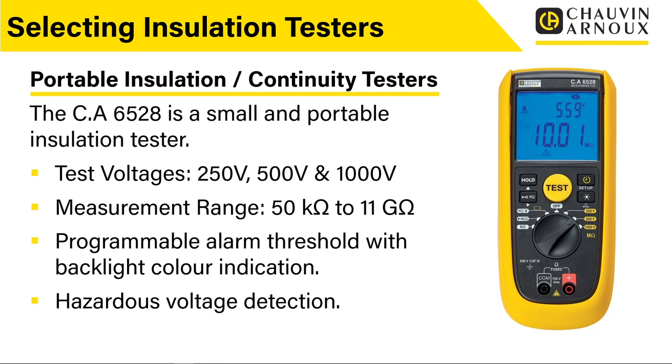Now this will carry out testing particularly suitable for the normal low voltage type insulation. So it'll do test voltages of 250 volts, 500 volts and 1000 volts DC. It's got a really wide measurement range, which goes from 50 kilo ohms all the way up to 11 giga ohms. So we're talking way up, above mega ohms, we're into giga ohms.